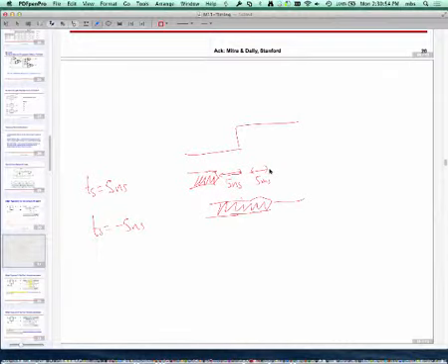No, if it is negative, all it is saying is that the data can change up to this point, and then it should remain stable for some time, and that comes from the hold time, for this clock edge to read the data successfully. Okay, and probably what is happening in a flip-flop like this is that internally, the hold time and setup time are defined relative to the flip-flop device that is given to you. But internally, if the clock has some additional delay before it reaches the actual flip-flop, then setup time could be negative. Okay? So that's what ends up happening.